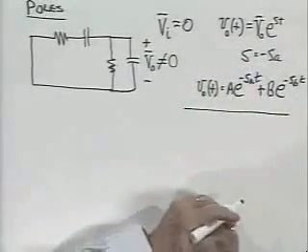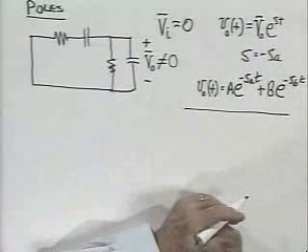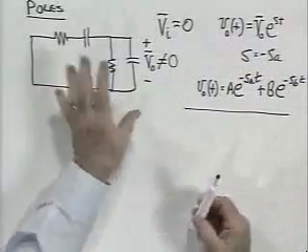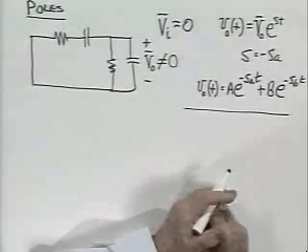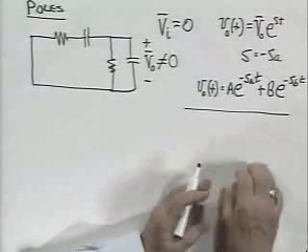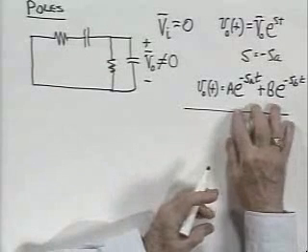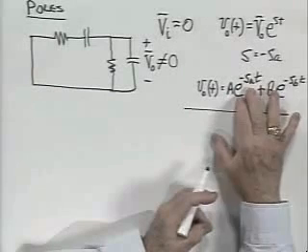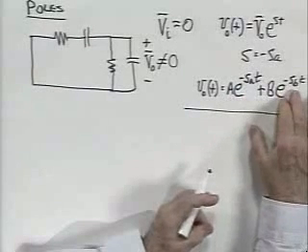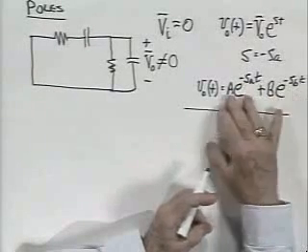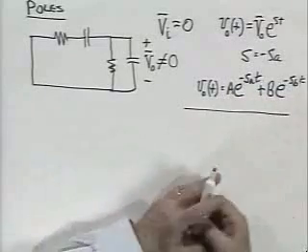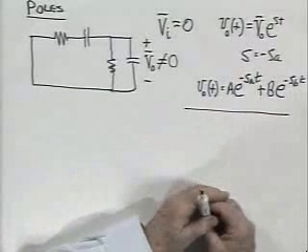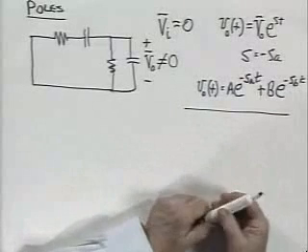And this is the transient response of the network. That is, left to itself, unforced, dump some energy in the capacitors and see what happens. You get a response which is the sum of two exponentials with different time constants. The time constant here, 1 over s sub a, time constant here, 1 over s sub b. Different natural frequencies, two different exponentials, and the general form of this voltage, V sub O, the natural unforced response, is the sum of those two decaying exponentials.